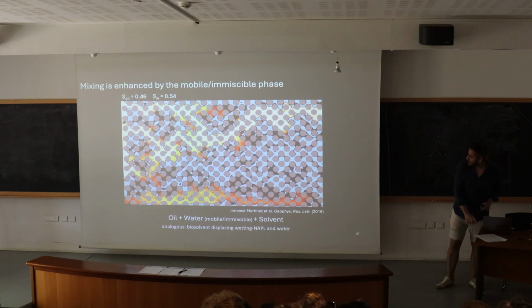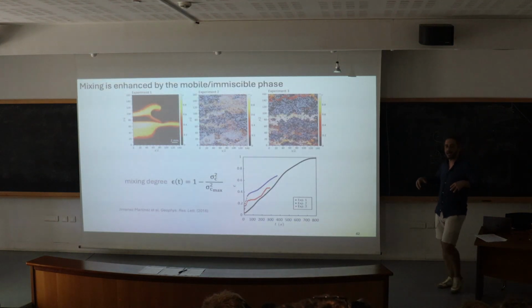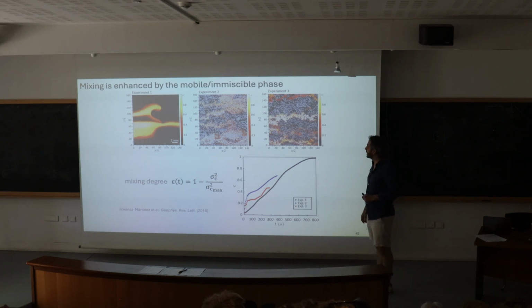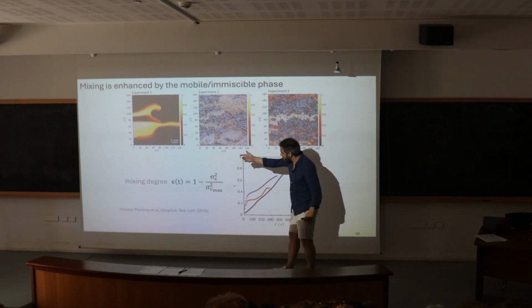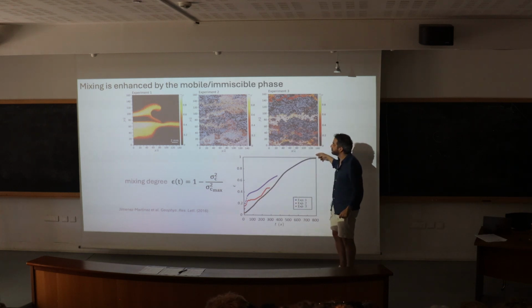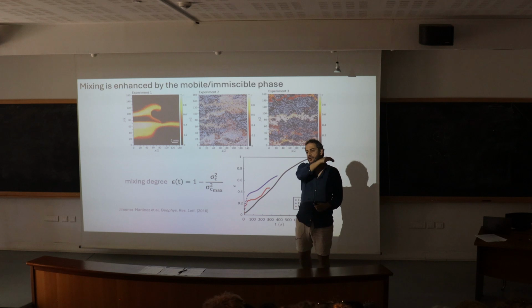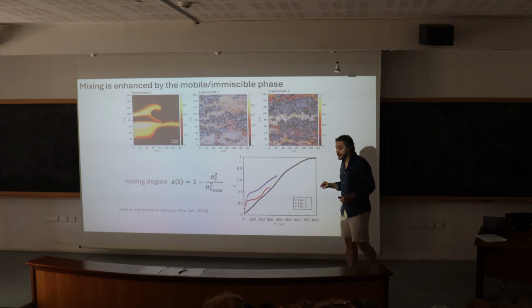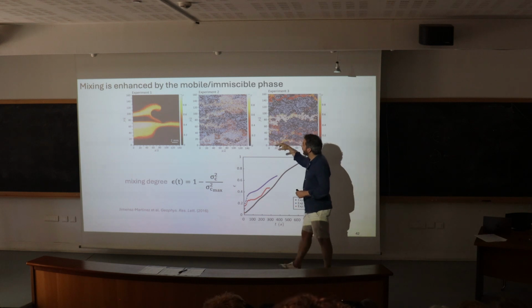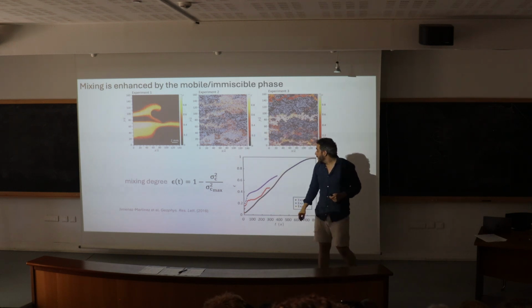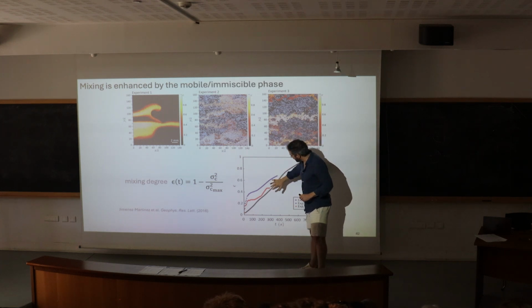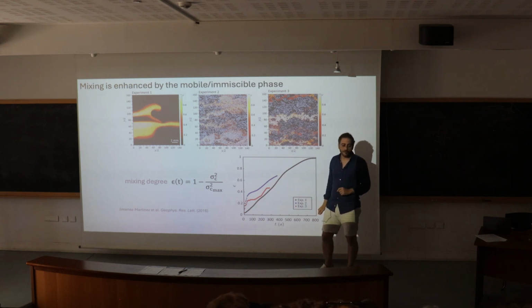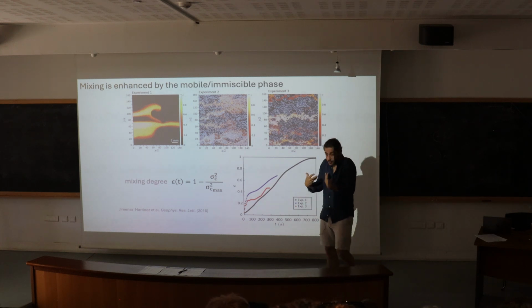Now if I repeat exactly the same experiment but with a lot of statistics, like in this microfluidic experiment, we can repeat the experiment with only the hydrocarbon and then inject the solvent. If we use this mixing degree as an indicator, at the end I fully clean my system: I inject solvent, and all the hydrocarbon goes out of the system. But if we have water here in blue color, like what happens in soils, we actually got a surprise, because for very similar initial conditions we can have very different evolution of the mixing degree, of how we mix our solvent with the hydrocarbon.